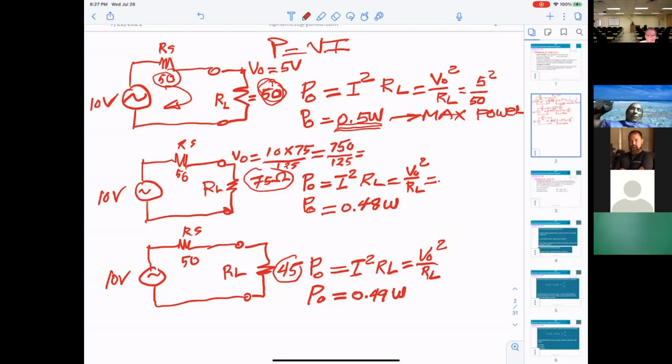However, when they want an amplifier for the load of another stage, and they say, okay, I want high loading or low loading, then they can use either CB or CC. If we want to know the detail, you have to go back and see CC and CB: which one has high impedance, which one has low impedance.